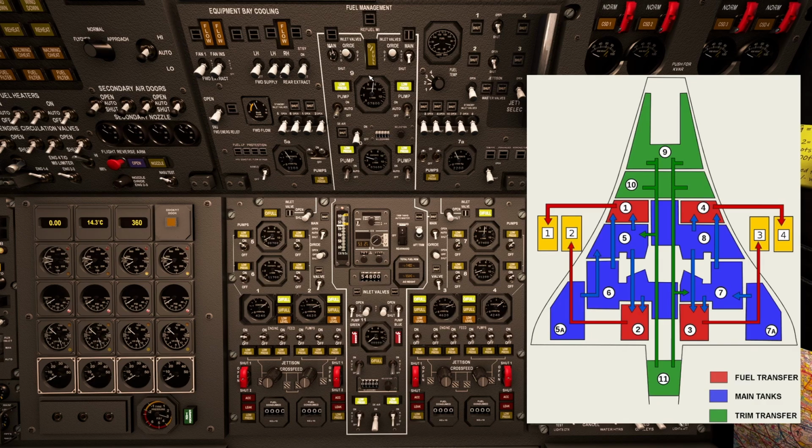we would pump fuel from the back to the front of the aircraft, and therefore change the center of gravity, which is indicated here in the middle, which is at 53.2% right now. It's trimmed to the front, which is okay for departure. And you also see the total amount of fuel that we have here in kilograms, 54,000 kilograms, which is correct because in Navmap and Microsoft Flight Simulator we had 120,000 pounds, which corresponds.